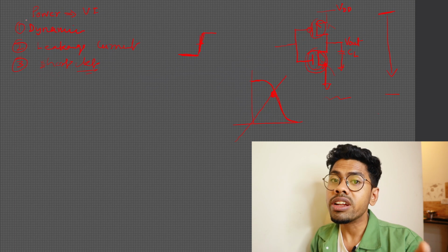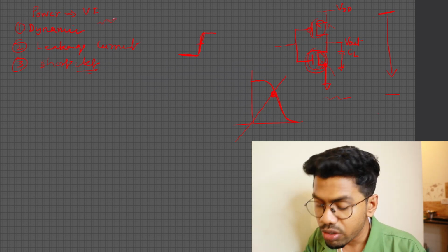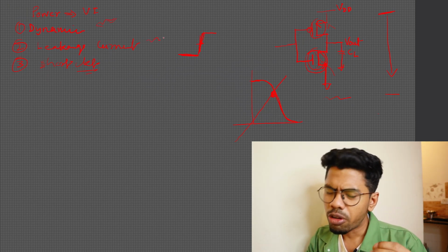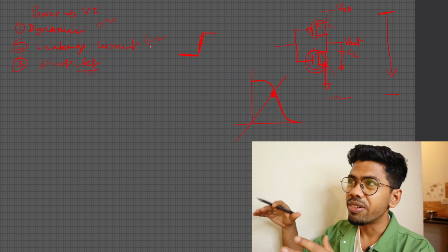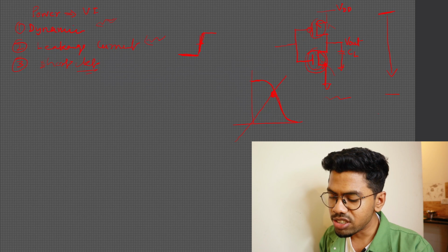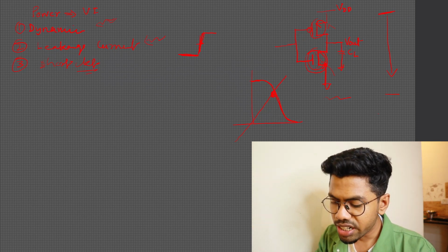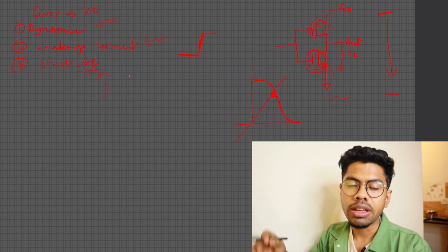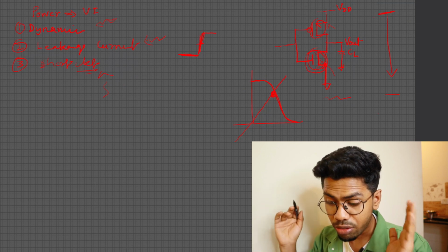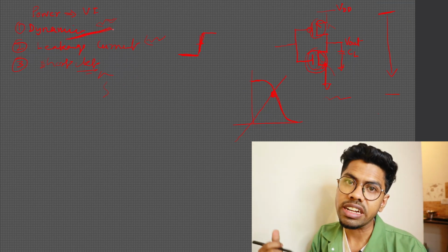One thing you can know from here is that from our design we can reduce dynamic power dissipation. Leakage also probably we can, but if the process is defined, we can't do much, so leakage is nearly out of a designer's hands. Short circuit currents we will also discuss. There are probably some ways for a designer to reduce that, but for sure dynamic power can be reduced by a designer.